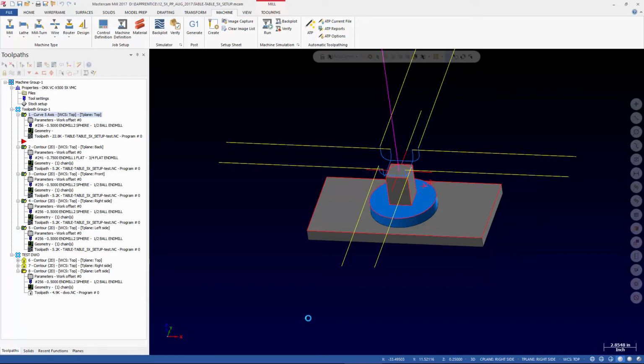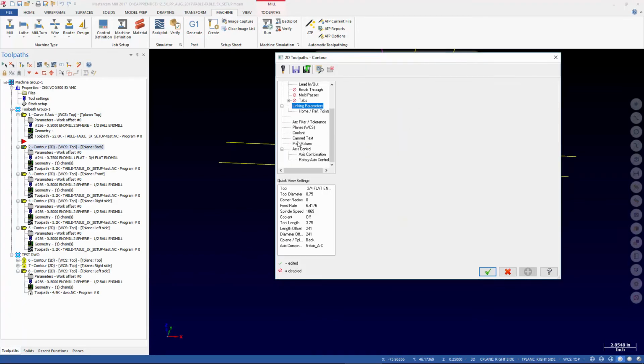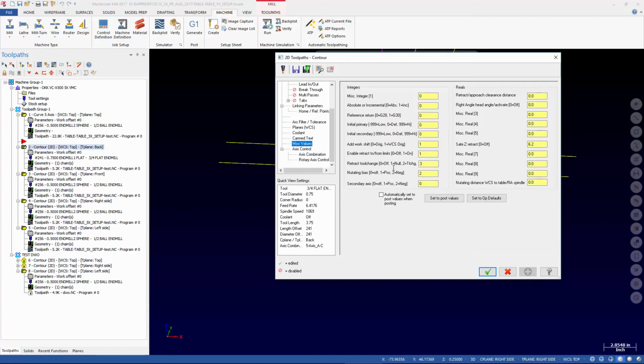How do we modify things like the tool change event? Where do we go to make our changes? What can we change? What does the post automatically track for us? We'll look at setting up different coolant codes, and setting up the few remaining miscellaneous integers, because if you notice, when we use the generic Fanuc post, most of these values are already used for us.